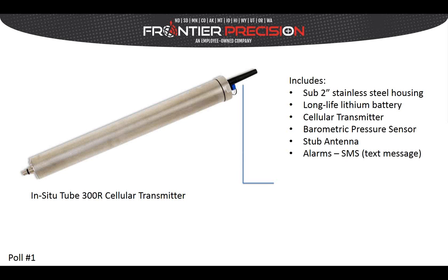The accuracies that you can expect to see are pretty much about 1/8 of an inch with our lowest cost pressure transducers that I used in the pricing structure. We do have higher accuracy ones that a lot of scientists, state, and federal government employees use for their work, because we use these same types of systems for groundwater level measurement, stream gauging, river canal measurement, lake and reservoir measurement, stuff like this.